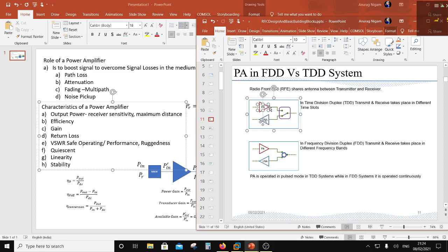So now what happens is thermal becomes important, right? So why is thermal important now? Because a PA basically takes a certain time to settle down and reach a certain junction temperature, and its gain is going to droop. So when the gain droops and you put out any linearly modulated signal, it is going to distort. So basically it has to wait for a certain period of time before the PA stabilizes thermally, right?